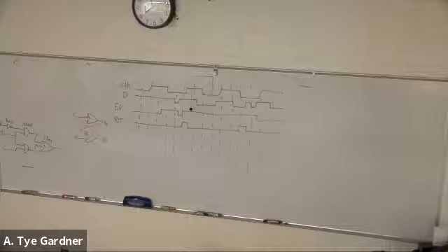Well, let's continue on. D is 1. So actually, it turns out it's 1. Why? Because either enable isn't on to write in a new value for D, or it is and D is already on. So either it's not enabled and it can't change, or it is enabled and we clocked in a 1, so it didn't change.